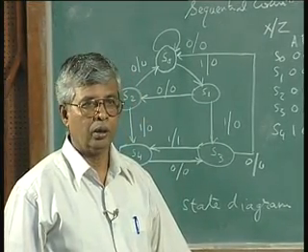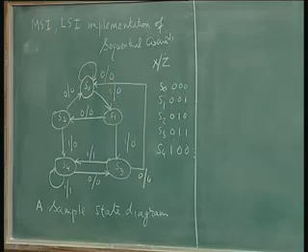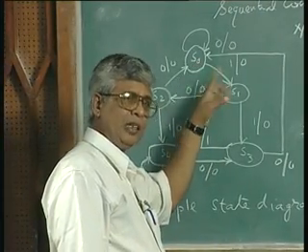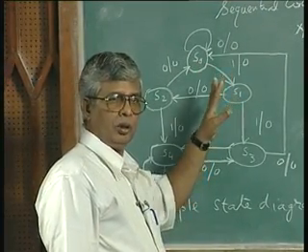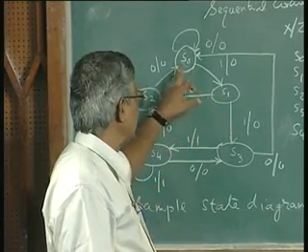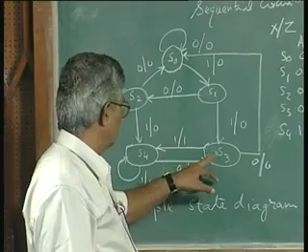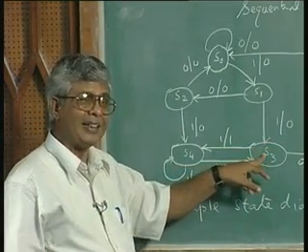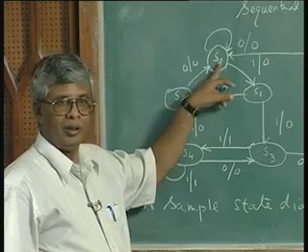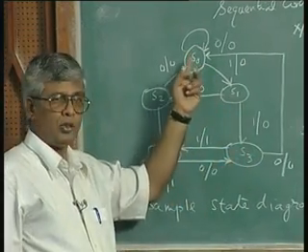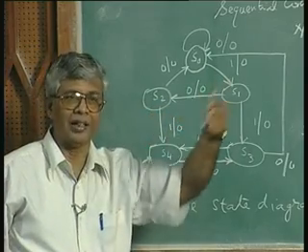Yes. So would the output correspond to the previous state? No, the output, according to the state graph, is defined by the present state and the input. If the circuit is in S0, this is what the next state is. Circuit is in S3, its input is 0, next state is S0. This arrow means from S3 it goes to S0, not now, at the next clock edge.